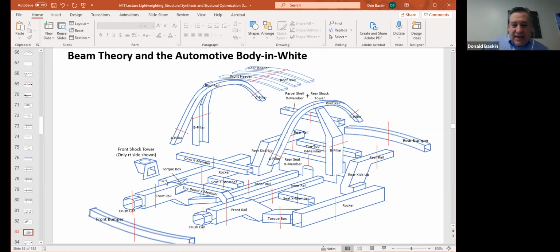I was involved with launching the Chrysler 300 and the Charger and the Magnum long ago. And during testing, we actually got cracks in this part. And we had to put on what's called a doubler, which is a secondary plate that goes, in this case, over the top to reduce the stress by adding more wall thickness. So this is the shock tower.